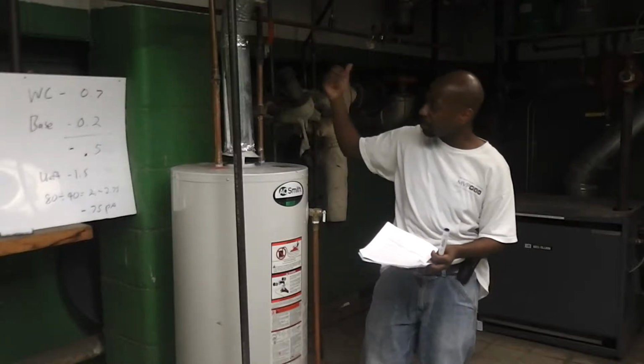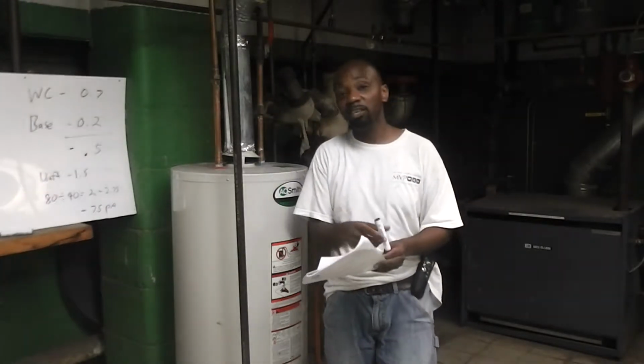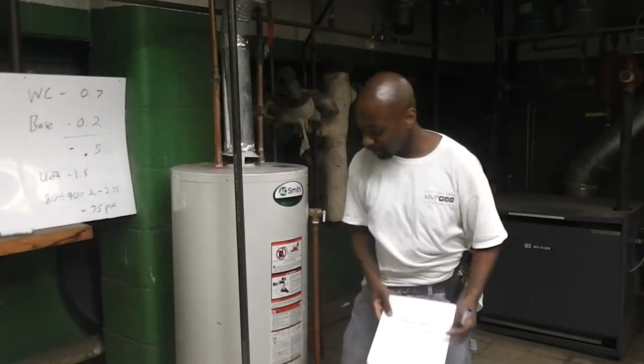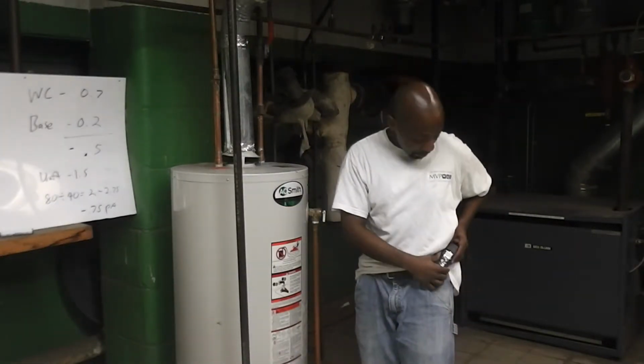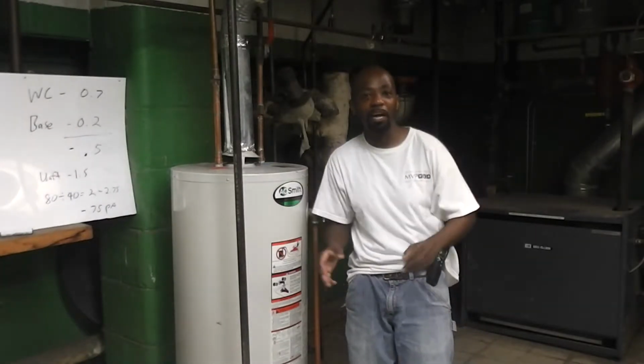So far we passed the worst case, we passed draft, we passed spillage. The next step is the CO, the undiluted CO. That's what gets generated deep inside the combustion appliance. Before I continue, I want to check my ambient CO. We are still good, nowhere near 9, nowhere near 35, so we can still continue.